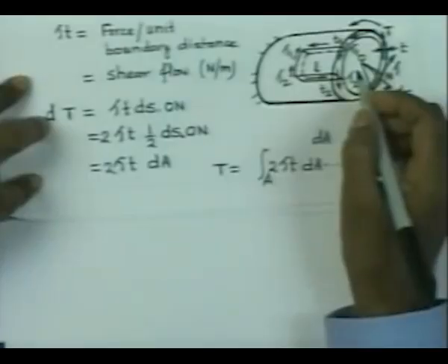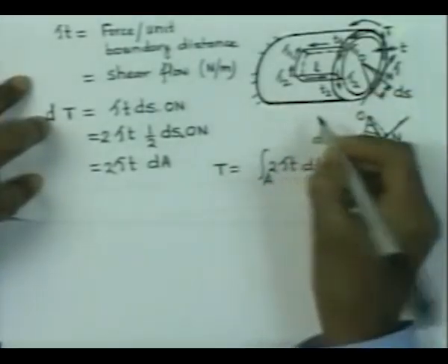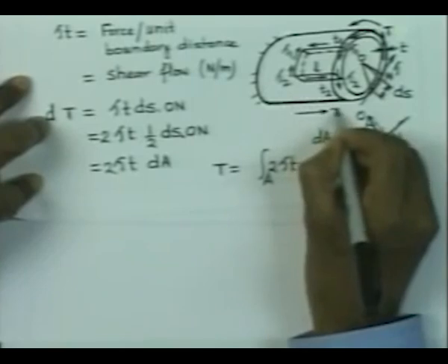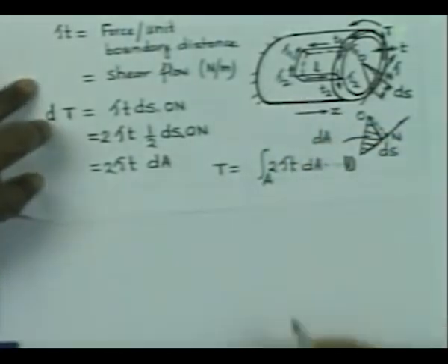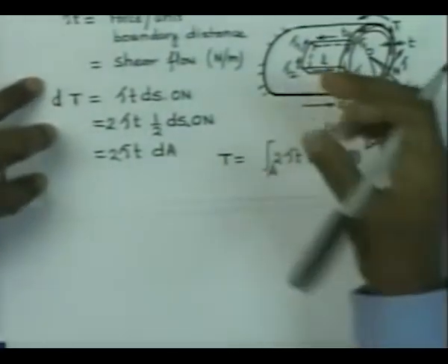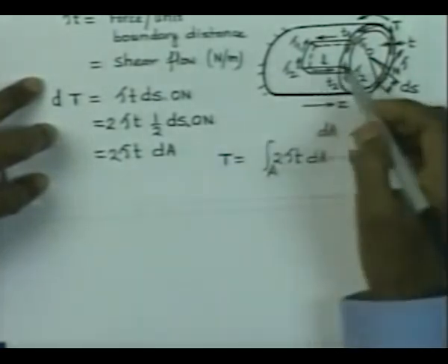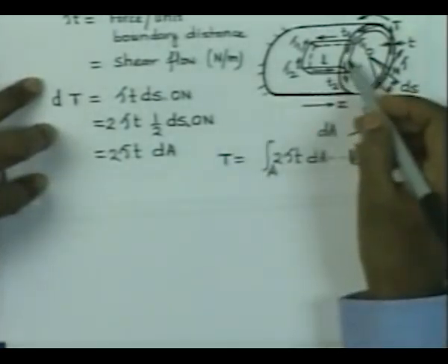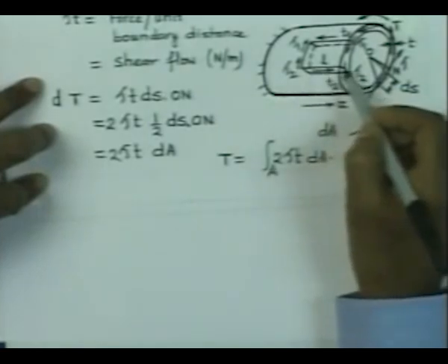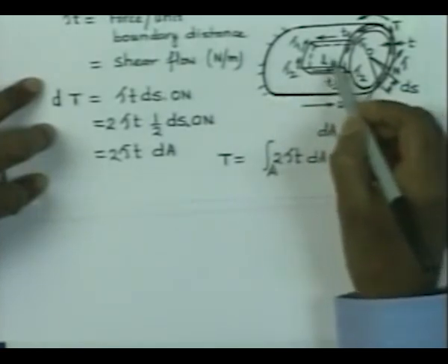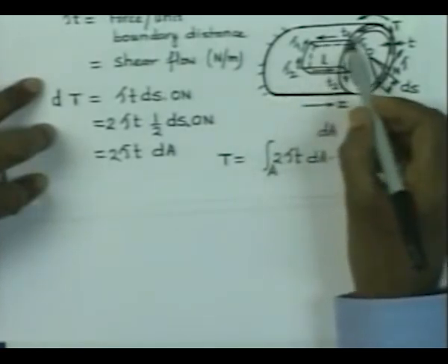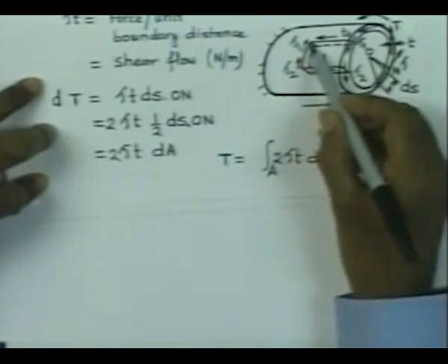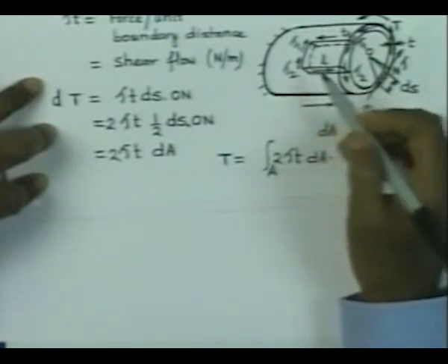So, if you would like to consider that axial direction is equal to Z, this is our Z direction, then sum of the forces on this element, just take it out and think of it that forces are acting on this boundary which are of intensity tau 1 there, tau 2 there, and on this face we have uniform stress of magnitude tau 2, on this face it is uniform stress of magnitude tau 1, and here again we have tau 1 here, tau 2 there.